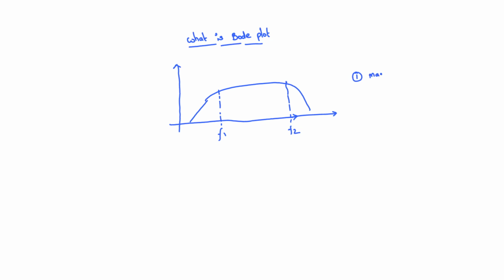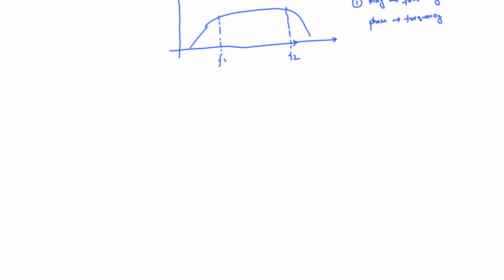So what is the purpose of it? As you know, when the magnitude reaches 3 dB, from that 3 dB we can say whether it is going into the amplification zone or the attenuation zone. From the previous example, when you observed, when the gain is 2, it starts from 3 dB. When the gain is 0.5, it starts from minus 3 dB. So we need to find that particular plus 3 dB or minus 3 dB point, which is very important in frequency response analysis.